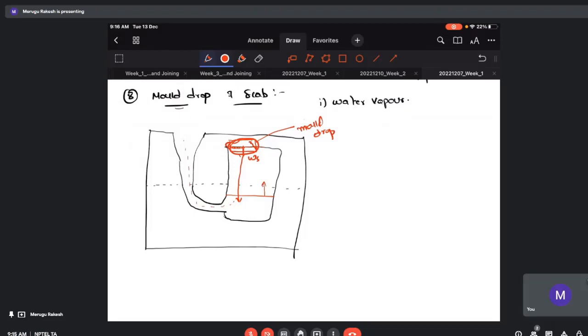By the time the metal moves up to the top of the casting, so till say till here, this mold will get sandwiched between the top and the liquid, and the mold will be present in here. So this is the big chunk of mold wall that is inside the casting, which is sandwiched between these two sides of the casting.